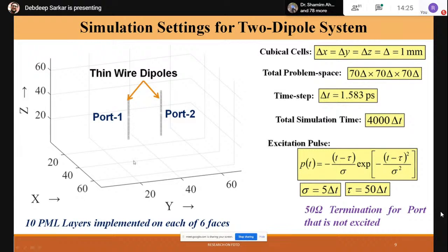Instead of considering this as a transmitter and a receiver, you can also visualize this as a two-dipole diversity kind of system acting in your cell phone, or maybe in some WLAN access point. So these are multiple antenna systems. I'll come to those things later, but this is the basic concept. My aim now is to focus my attention on carrying out the analysis of this two-dipole system to find out the scattering parameters for the time being.